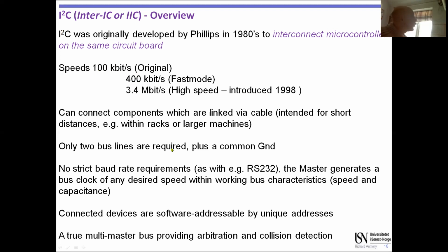This only uses 2 wires instead of 3. So whereas the SPI was a 3-wire system, this is a 2-wire system, and this is a bus. It's not a one-to-one system. This is a one-to-many or many-to-one system, and therefore devices need addresses. So we're now essentially a kind of networking where each device has its own address, and any device can become master. That's another thing that can happen. The one that is master at any particular time can talk to whichever other device it wants to.